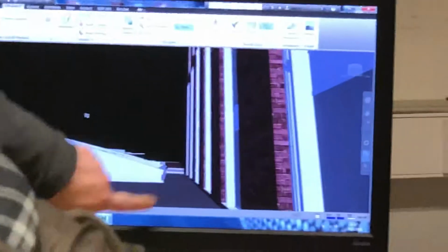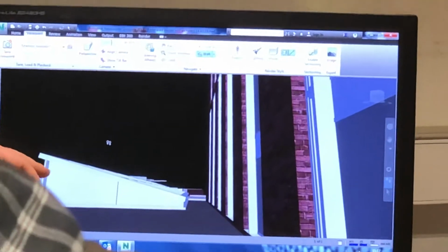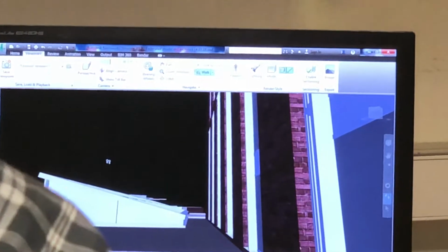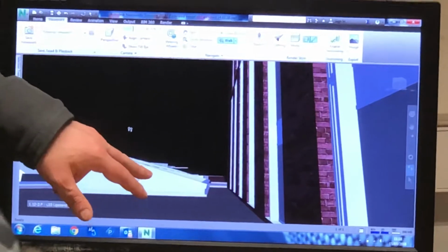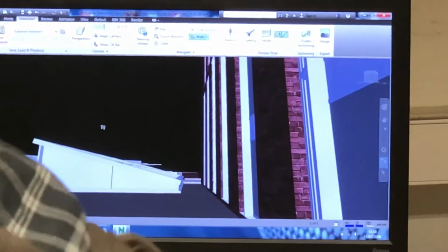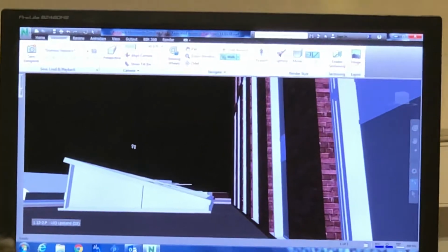It also allows us to, on the old model, which you guys haven't seen, I've just updated this roof light. It had steelwork there and it didn't have a pitch on, there was another piece of steelwork popping out to the end of it. What had happened is the curtain waller or the roof light designer had designed it with a fall as they would. They've issued their information to the architect and the structural engineer. They've then imported it into their model, but they've not changed the steelwork around it. And that allowed us to see very, very quickly there's an issue with the steelwork there. That's then been resolved within the model space before you get it to site and there be an issue with it. Okay?